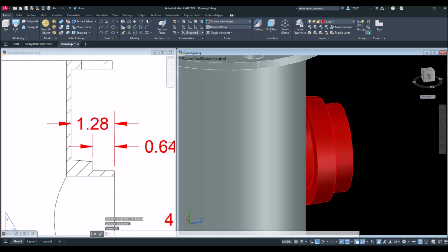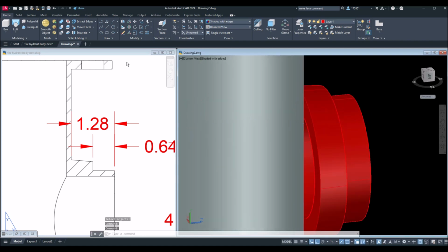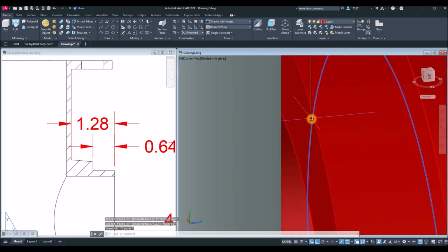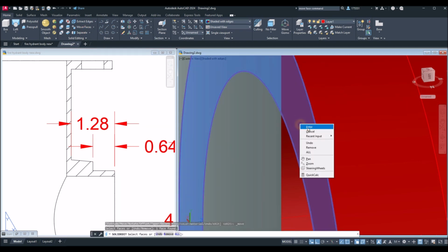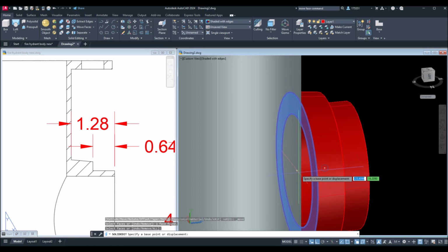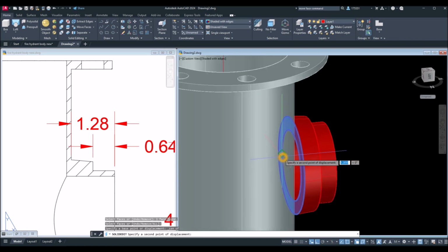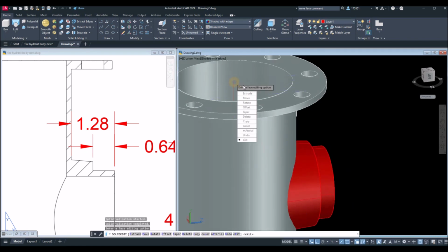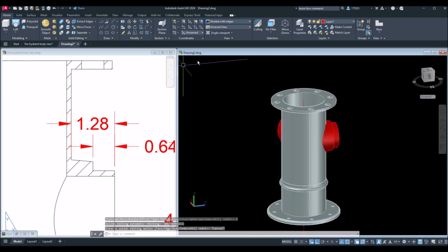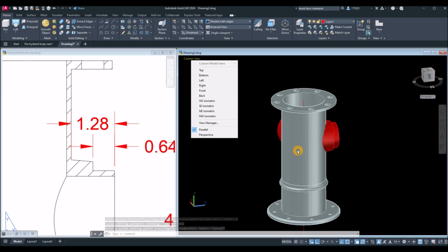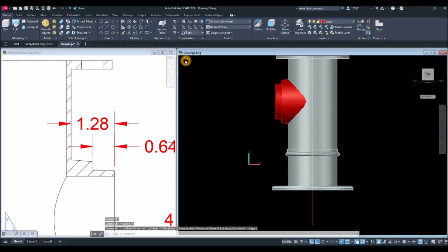Now the same process, I'm just gonna pull this face. So I'm gonna use move faces again. Click that, move this closer. Click this face, enter, and base point from the center here. So shift right click, center, and then click this in point here. And there are two nozzles that are equal, so I'm just gonna use this view here. Not that one, front view.